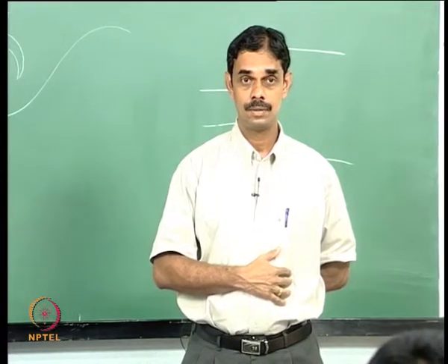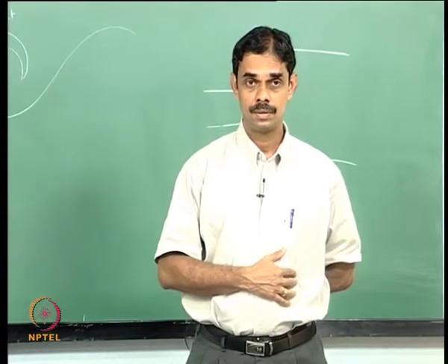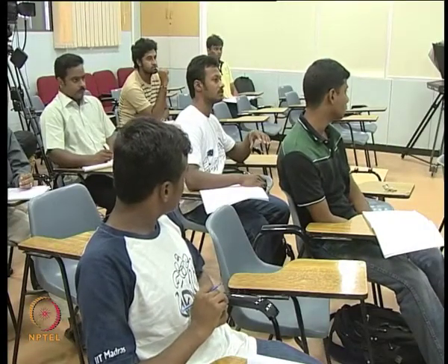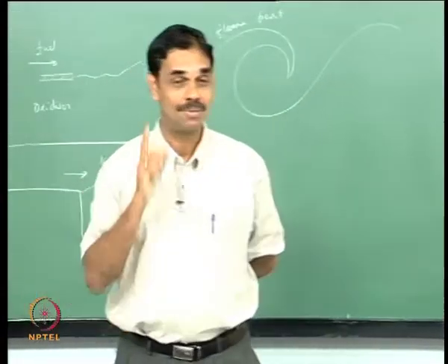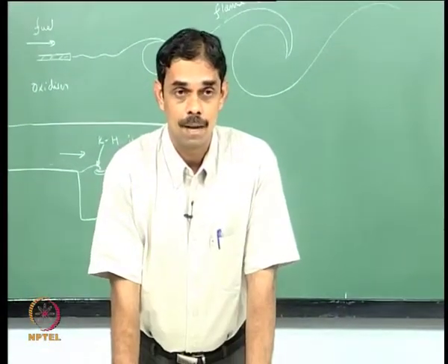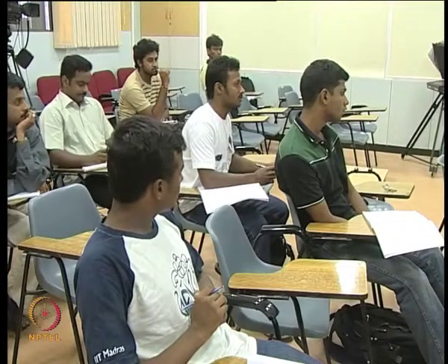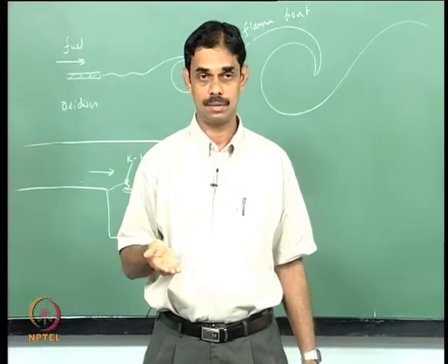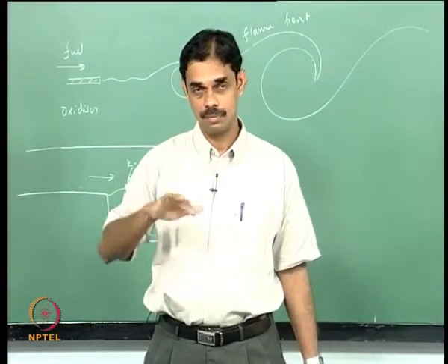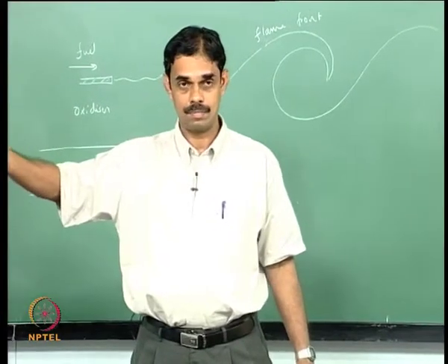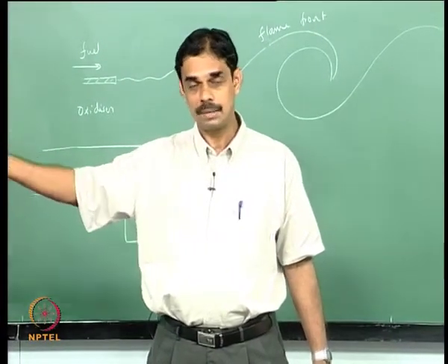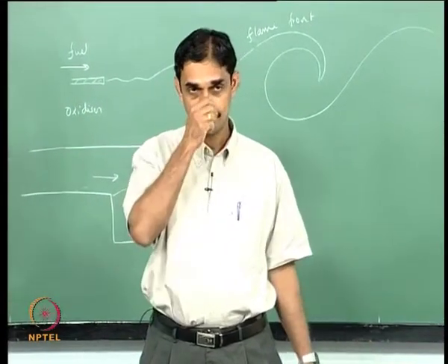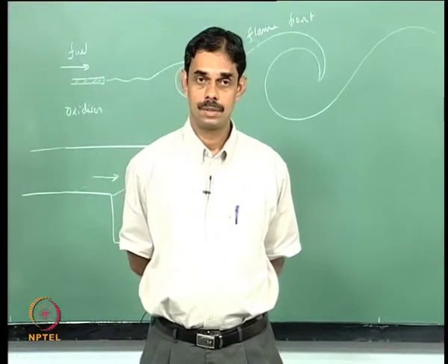The instability is basically from transition from laminar to turbulent. Only when the shear layers completely transit to turbulent. Can you repeat? You are asking a very deep question, so I have to pay attention. So the Kelvin-Helmholtz instability, it's basically during the transition from laminar to turbulent. No, you can have Kelvin-Helmholtz instability for laminar shear layers also. The shear layer will be unstable and roll up, and then it breaks down to turbulent. It will in a practical combustor, but you can have it not break down also and still be Kelvin-Helmholtz instability.